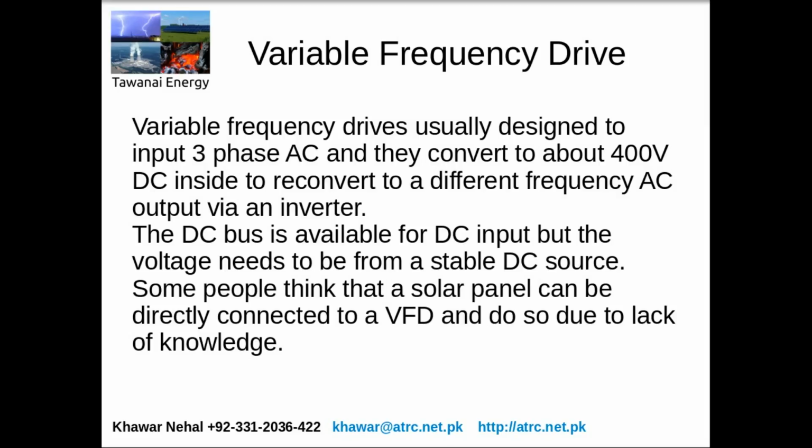Usually variable frequency drives are designed to have an input of 3-phase AC. Some have a single phase AC input. They convert that to around 400 volts DC, and then they give it to their inverter portion, which converts it back into AC, but based on the speed that is required, and that can change. It can change the frequency of the AC that's created.